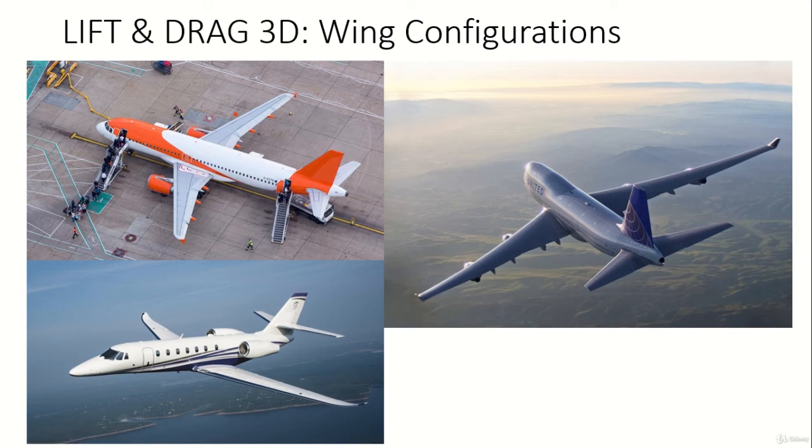So these are some examples of wing configurations that you may encounter. Usually, as we saw, we have tapered wings. In this kind of wing, you can see the root is kind of big. The chord at the root is quite large compared to the wing tip, right? And you can also see that there's some kind of wingtip used. Not much. It's quite small, but in most cases this is enough. You just need some little element to provide the difference in pressure, as we saw before.